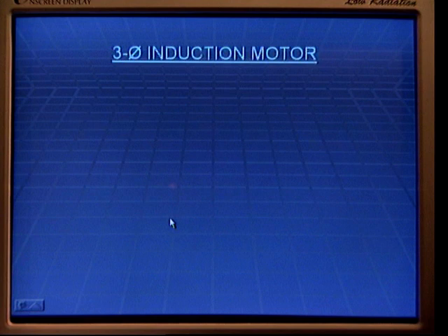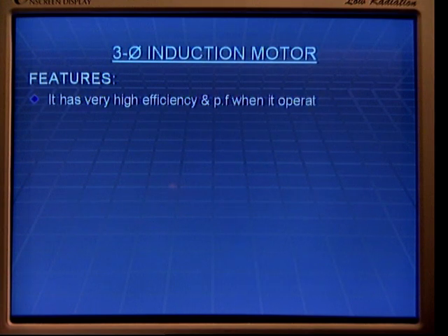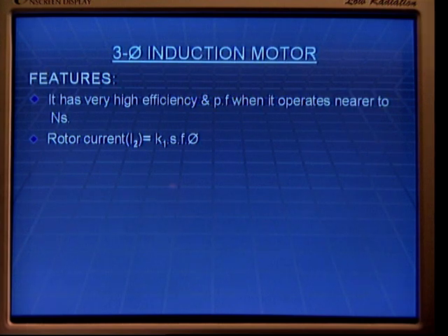So what are some merits? How are we going to get the high starting torque? You can see here some features of 3-phase induction motors. It has high efficiency and power factor when it operates near synchronous speed. And in the last slide we have seen the starting torque is high, without drawing any extra current from the supply. How is it possible?